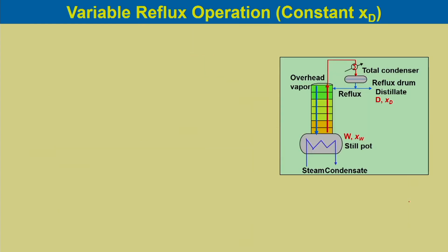Now, let us consider the other case, the variable reflux operation. In the variable reflux operation we keep the distillate composition constant, that is, xd is constant.